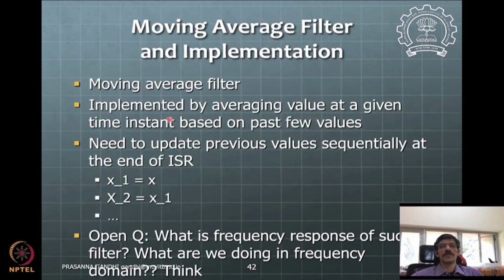So when we have to implement this filter, we'll see how it can be implemented. One of the ways of implementing a filter is this moving average filter. Okay. So the moving average filter will have a formula. What you'll do is, at a given point, you'll consider the previous two or three or more samples and take an average of all those samples and keep it at that value.